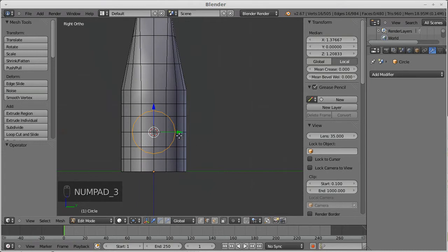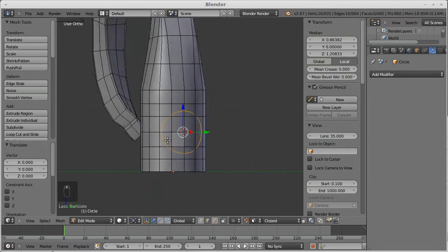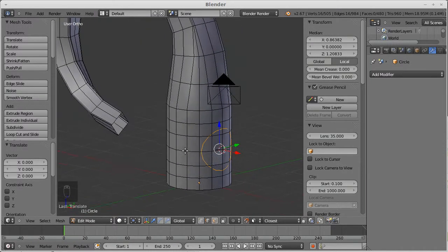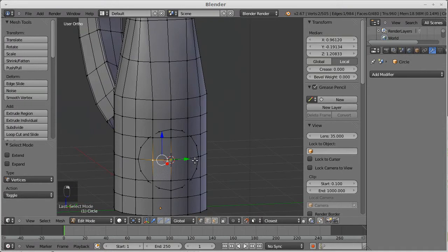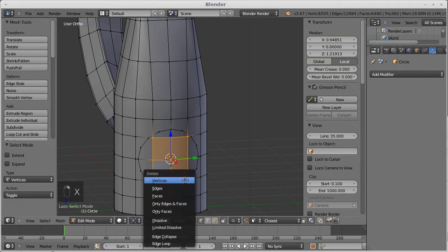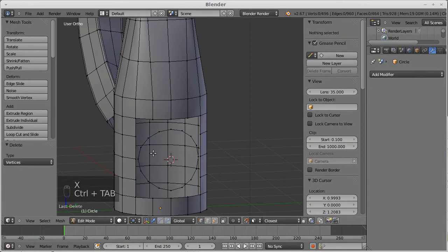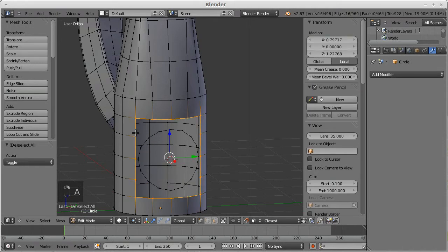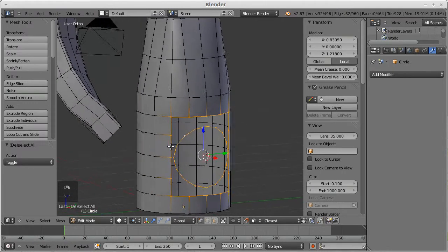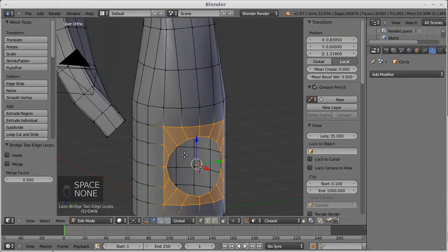So, let's start drilling. We need to project this on the face. G, don't touch anything else. Press enter. Okay, it's now on the surface. Let's start getting rid of points. We have a 16 vertices cylinder and a 16 vertices loop, so we bridge it. It's as easy as pie.